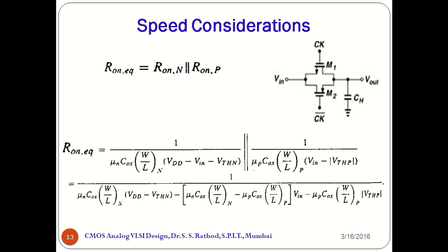So now how to solve this problem? What we do is we can connect one NMOS switch in parallel with the PMOS switch.